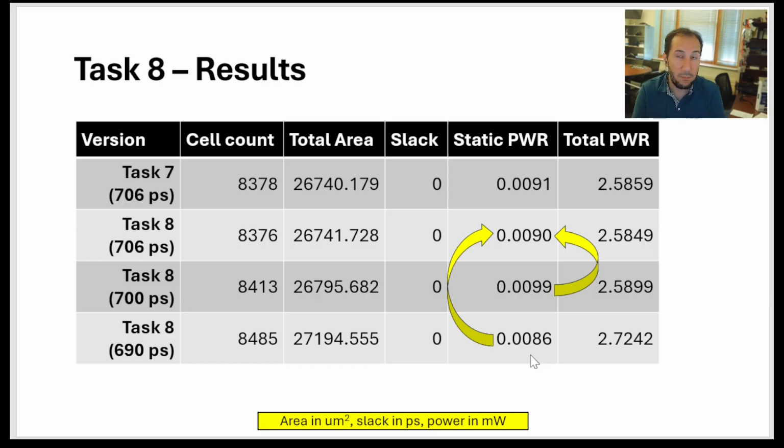So now, proportionally, the cells spend more time burning dynamic than burning static. And that's why this number goes down. If we keep increasing the clock frequency, eventually this number tends to go to zero, which is insane. But it goes to zero because the cells are active all the time doing something. Okay, it is what happens.